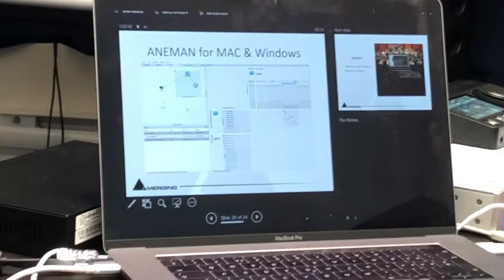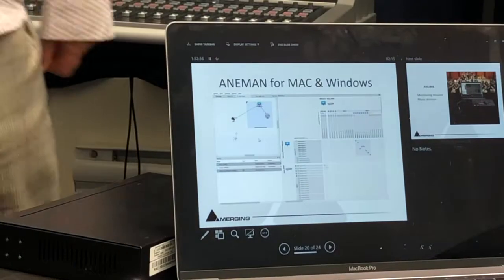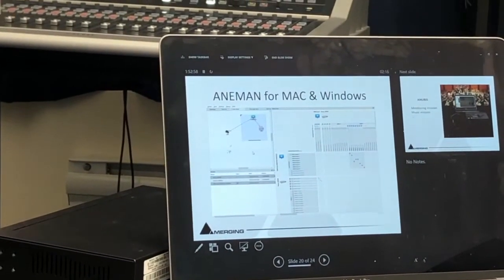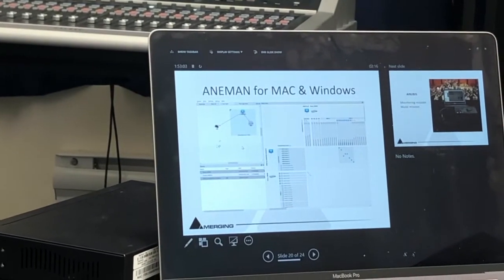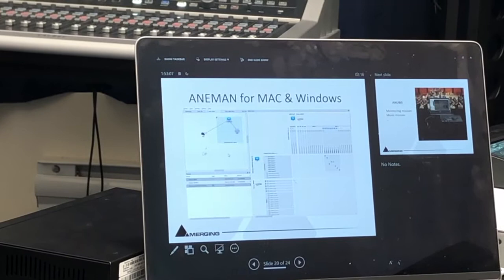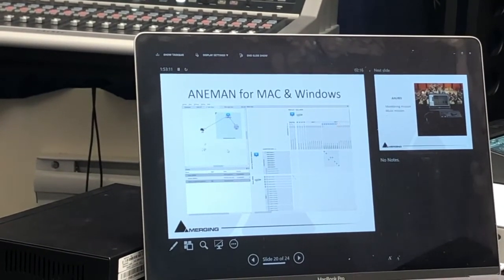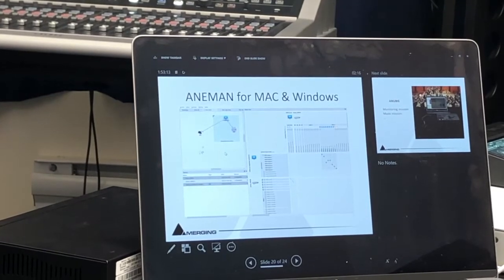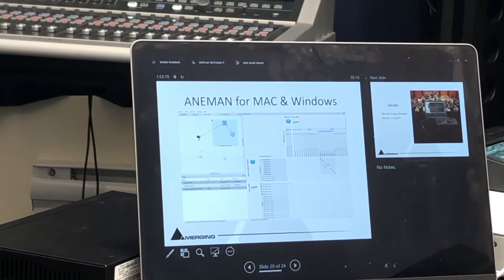And the second thing is that we don't see it that well on that screen, but here you have a gray area actually. You can make it green if you want, but called sample rate zone, and you can create several sample rate zones. That means that you elect a king or a queen that is master of that sample rate zone, that you put where the crown is on the top, and that means that all the devices that you put into this zone inside, when you change the sample rate of the queen or the king, it will change the sample rate of all the devices at the same time.